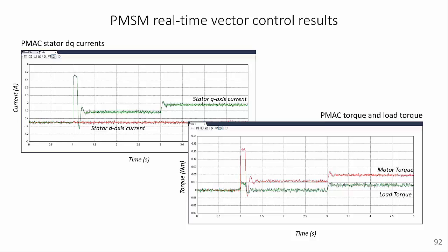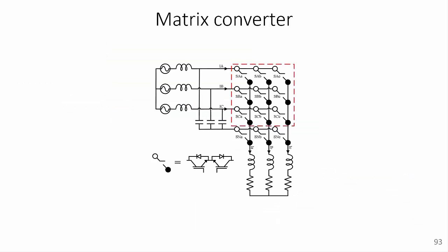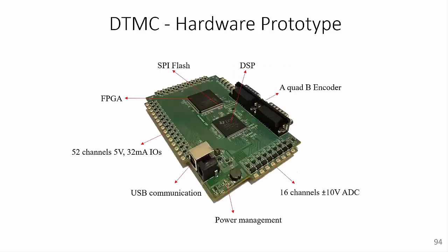One of the interesting applications that we are using in our labs right now is to use Workbench and its code generation feature to run a matrix converter hardware in real time. Here's the image of a 3-level neutral point clamped matrix converter that generates desired output voltage at desired magnitude and frequency directly from a 3-phase input voltage. This converter consists of 12 bidirectional switches, which are implemented using 24 discrete switches, where 2 switches are connected in common emitter configuration to generate a bidirectional switch.